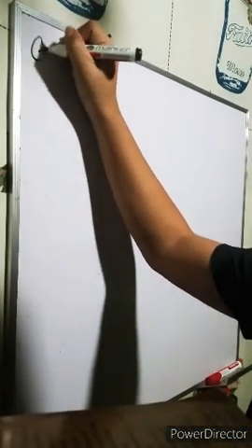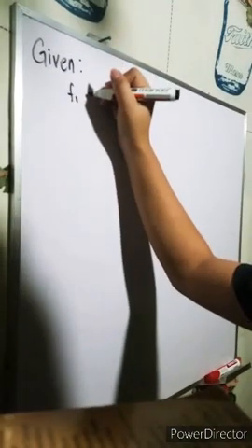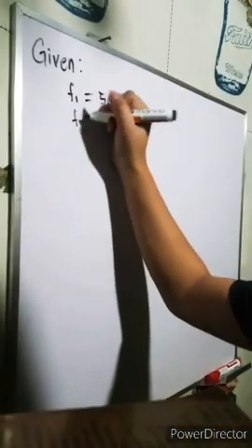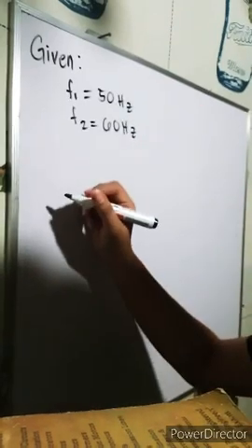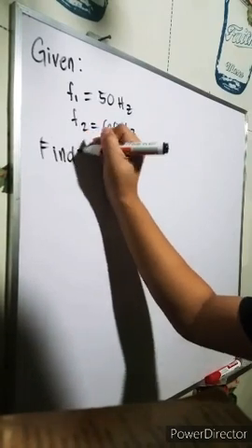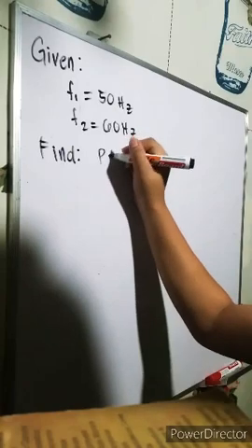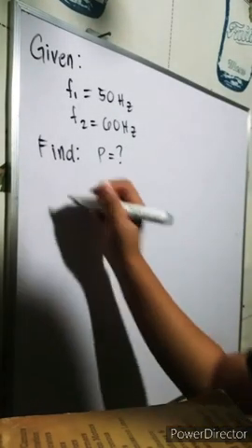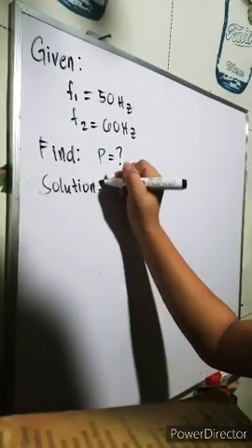So the first problem in Unit 3 is, in some places it is necessary to supply 300 kilowatts of 60 Hz power. The only power sources available operate at 50 Hz. It is being decided to generate power by a motor-generator set. The question is, how many poles should the machine have in order to convert from 50 Hz power to 60 Hz power?